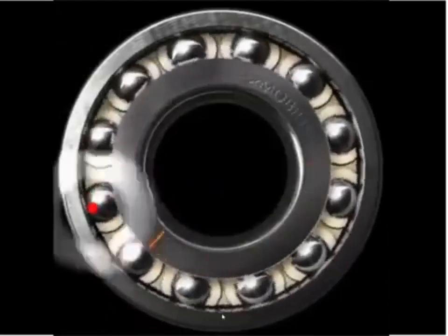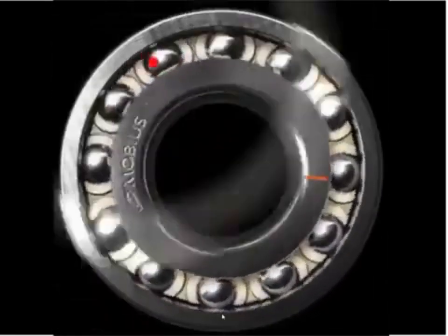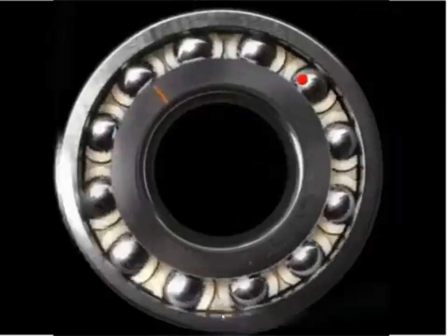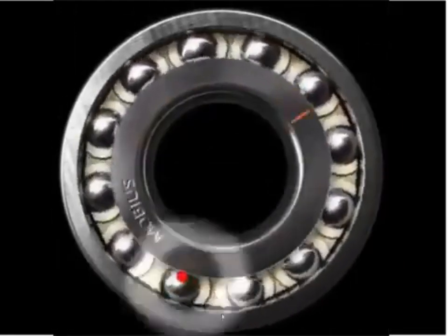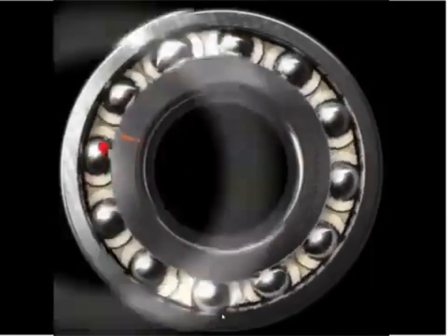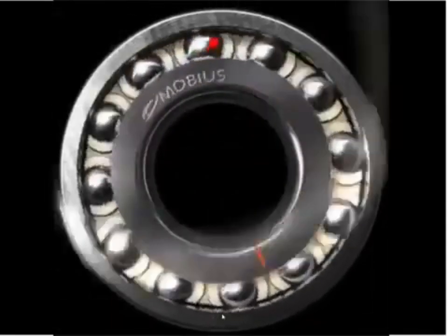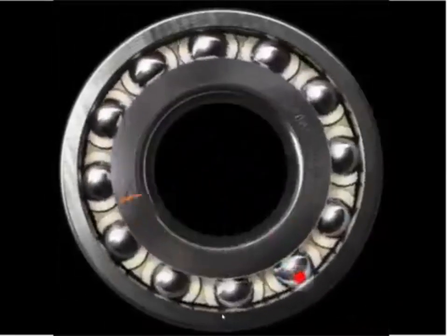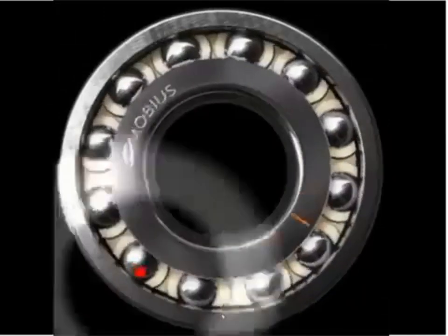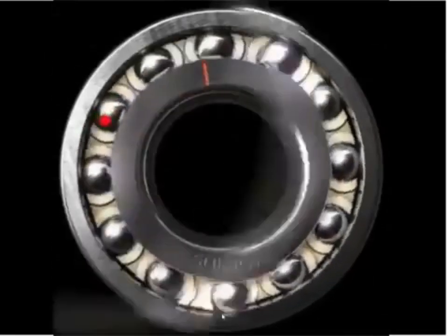And that's why a vibration analyst doesn't just say, oh, there's bearing damage. The analyst can actually say whether it's on the inner race, outer race, or on the rolling elements. Now, it's not that you're going to go and buy a new set of rolling elements or a new inner race or something like that. But knowing that information can really help in the planning and scheduling process.